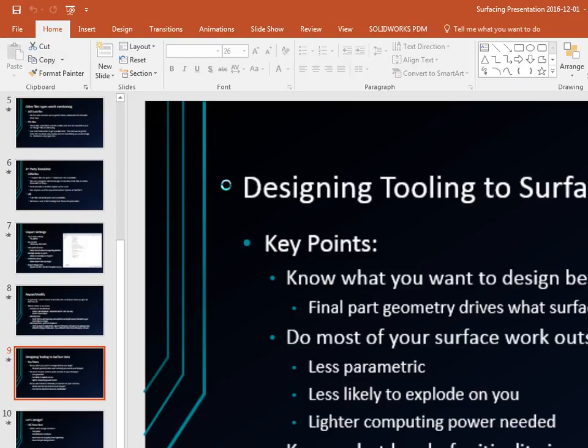Once it comes in. So now that it comes in, I want to do a split line on these surfaces so that I can find where it's tangent to my die draw. My die draw is in the straight Z direction in this case.